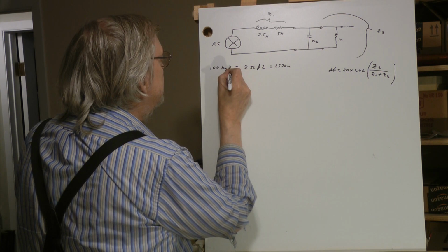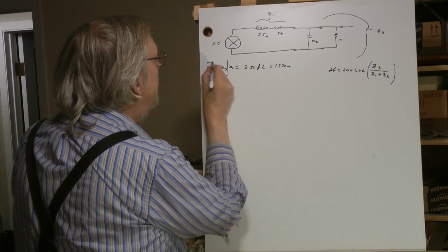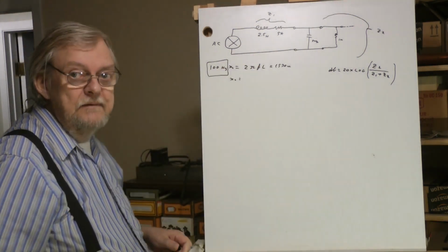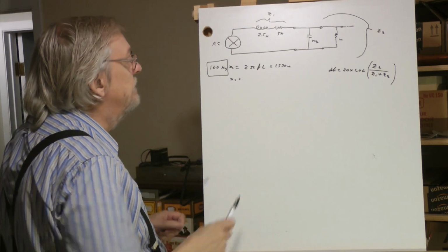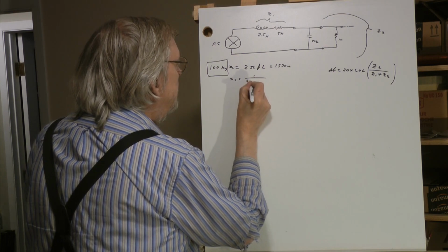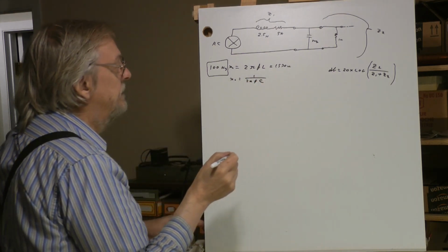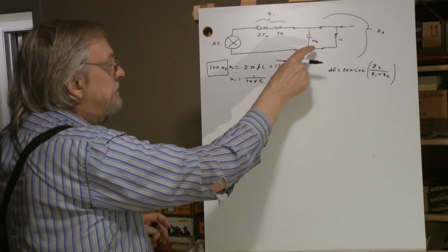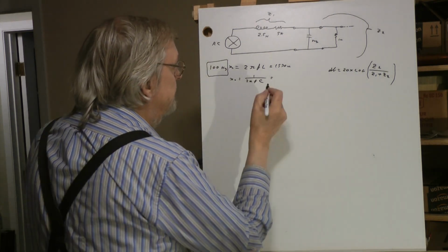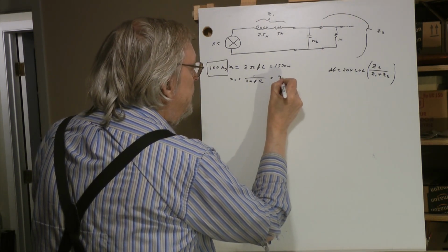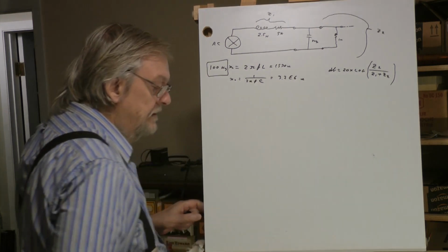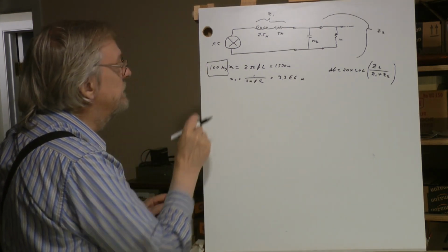So the formula, I'm going to put in here XL, right? XC, the effective capacitive resistance. It's called capacitive reactance. It forms an impedance. The formula is 1 over 2 pi times frequency times capacitance. Now at that frequency, with that small capacitor, that's going to be very high. It's actually 3.2 million, so 3.2 times 10 to the 6 ohms. 3.2 million ohms at 100 Hertz.